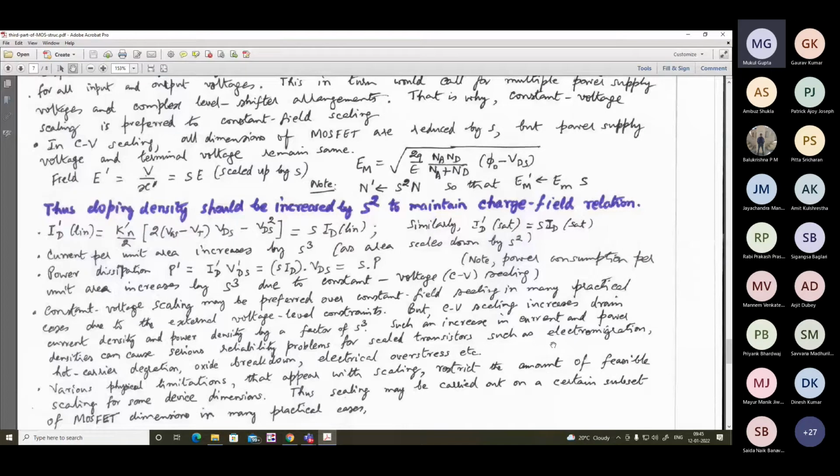The metal ions tend to migrate towards the direction of the current, and if they do so, it will lead to gradual reduction in the width of the metal wires, particularly over a very restricted region, but eventually it may lead to simple discontinuity of the metal wire.